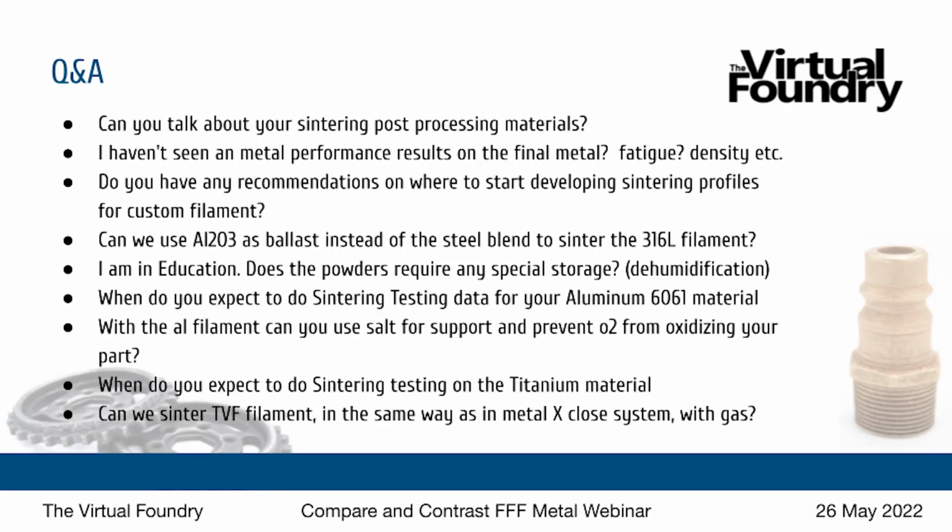In the first part, during the sintering process, we use a technique we call ballast. We take the part and essentially bury it in sand. The sand supports any part that might overhang or distort due to gravity or the material shifting during the sintering process. You also have to account for shrinkage, which causes some shifting in the material right around the part. What we use is Al2O3 or a combination of Al2O3 blended with high purity graphite.